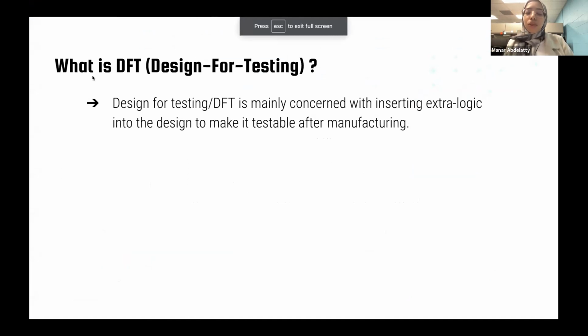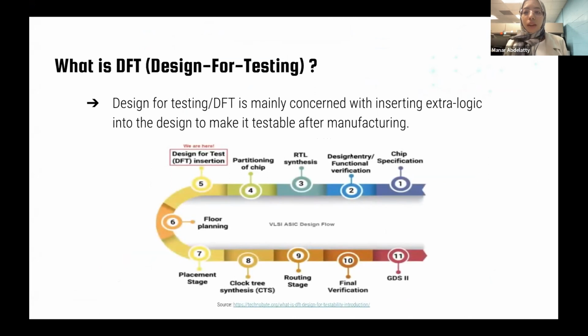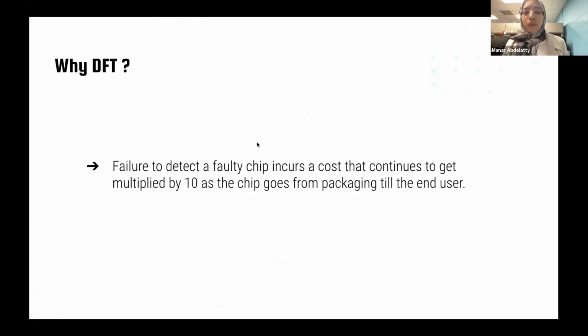To start with, what is DFT, or design for testing? DFT is mainly concerned with adding extra testability logic into the design in order to make it testable after manufacturing. Putting this into context within the ASIC design flow, you will find that the DFT logic insertion step comes right after the RTL logic synthesis and partitioning of the chip, and it happens right before the floor planning step.